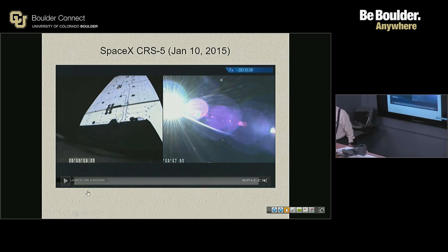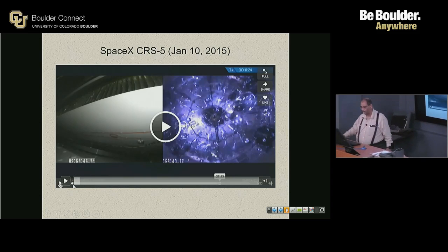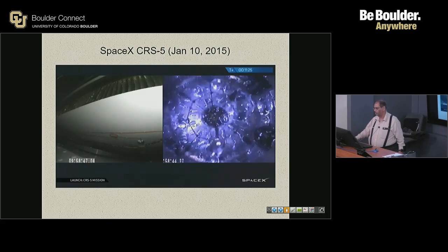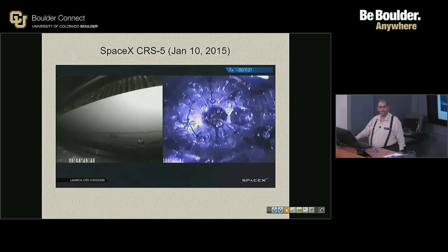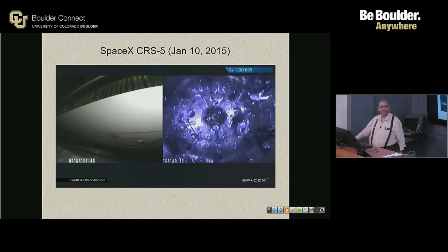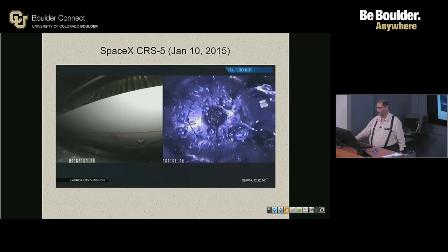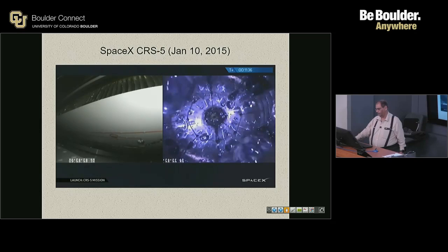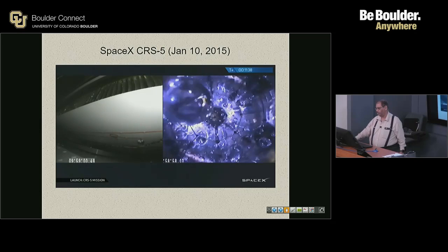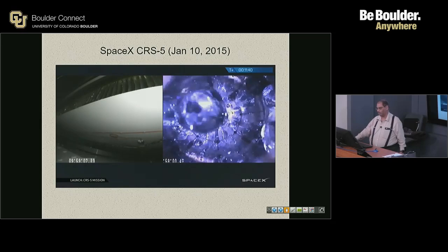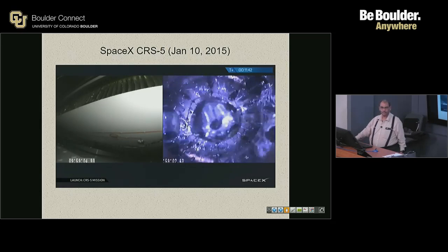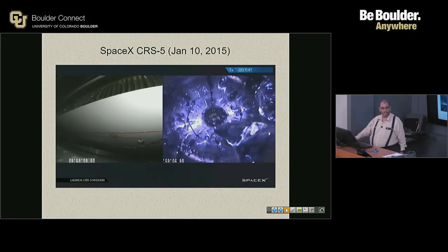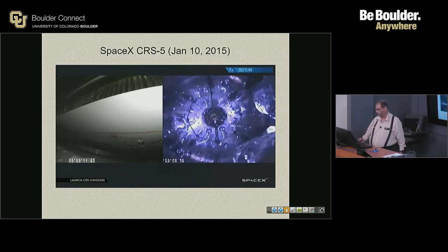So where is that? Oh, yeah, I think it's early in the beginning. See what the propellant looks like when the engine has stopped thrusting? You can't have that, right? Anyway, it is usual to provide a slight amount of thrust by whatever means in space so that you have some gravity acting on the propellant so that you can feed liquid propellant into the engine for space engines.